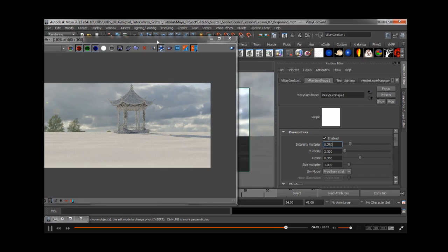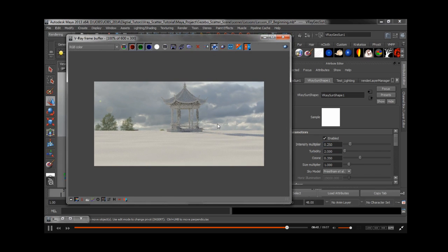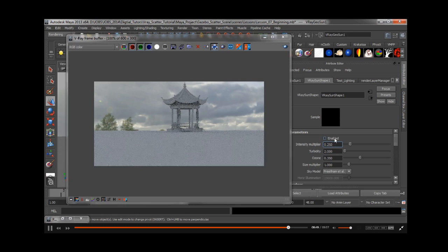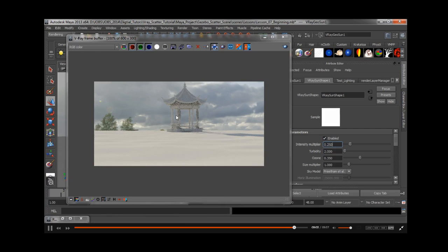And what we want to get out of this is this additional shadow, which we did not have. If I turn off our HDRI, we can contrast up our HDRI and push it much further in the intensity to get a stronger shadow, but it's nice to get some reinforcement from the sun as well. So let's just let this clear up here. Even at 0.1, we'll still get the shadow and the lighting won't be affected too much. So I think we'll leave that here for now.